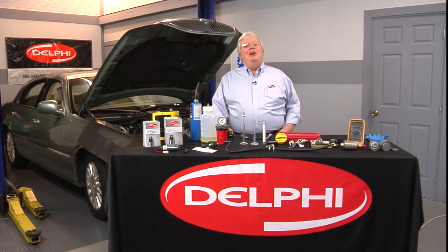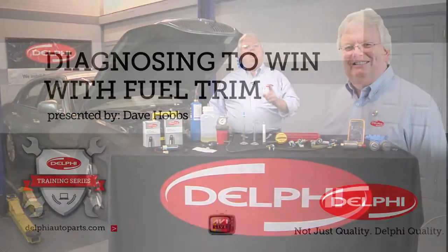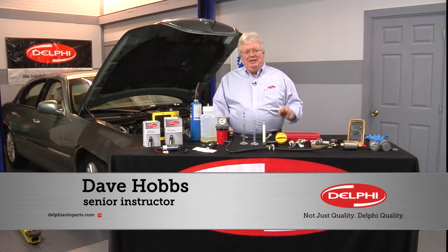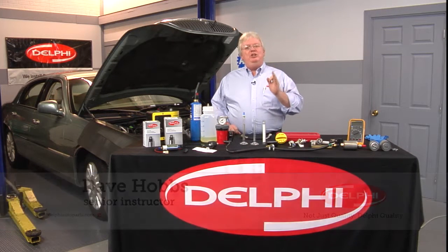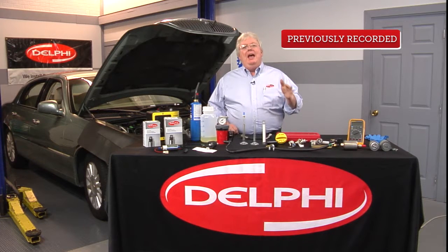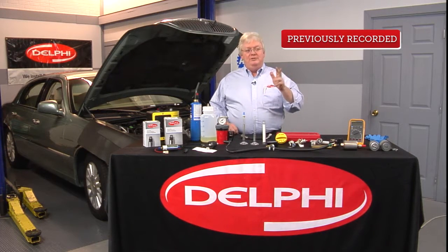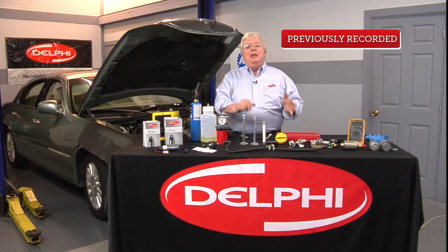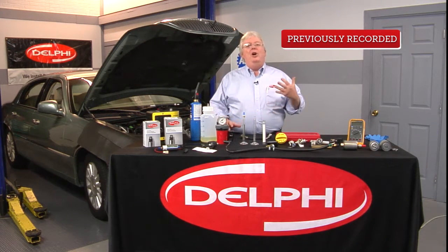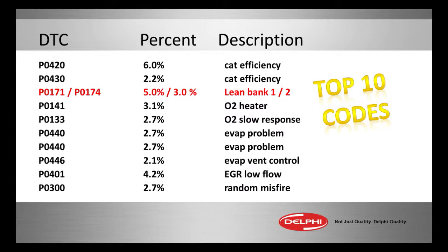Hi, I'm Dave Hobbs for Delphi, and welcome to this program on Diagnosing to Win with Fuel Trim: Maintaining the Mixture. Now, why are we getting into a program on fuel trim? Because it has to do with not only rich codes, but lean codes, and lean codes are in the top 10. Actually, they come in at number 3, the 171s and 174s, generic for lean left bank, lean right bank, or lean bank 1, bank 2, plus all the other manufacturer-specific P1 and other number codes that have to do with air-fuel mixture.